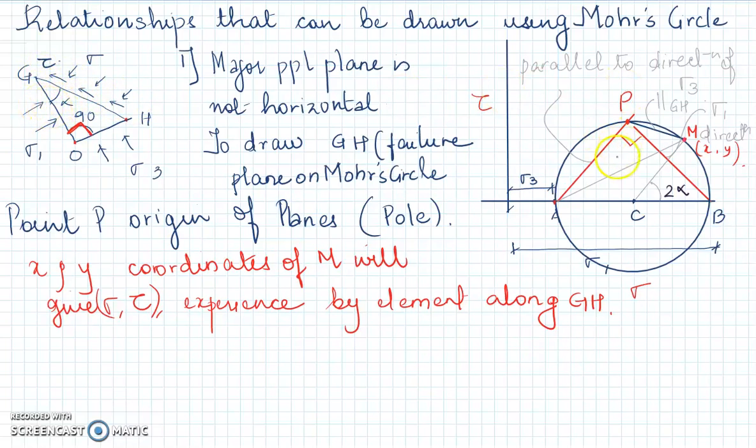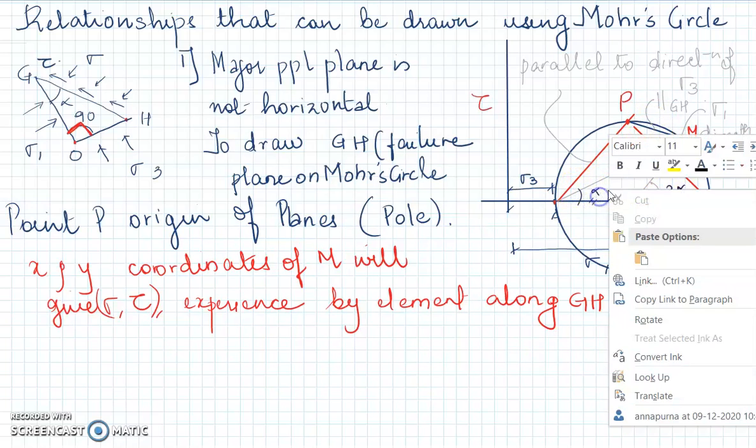So from the Mohr circle, even if the value was not given, just connecting M with C and B, you would get the value of 2 alpha. And now you know this is the radius, this is also radius, this is an isosceles triangle. So by geometry, you know this is alpha.